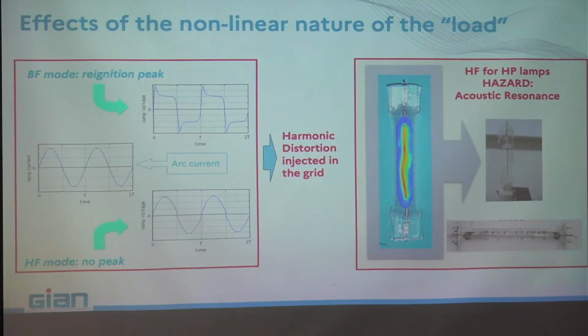Even the external bulb goes with the bang. Well, and the problem is those frequencies. In fact, this is a real photo, but what you see inside is a simulation. It's a MATLAB code calculating the acoustic resonance frequencies. Those frequencies depend not only on what is inside the lamp, but they depend on the geometry of the lamp, and they depend on the power also.